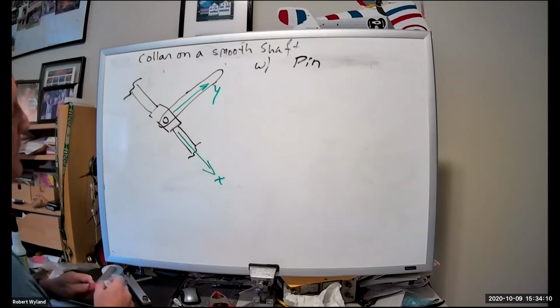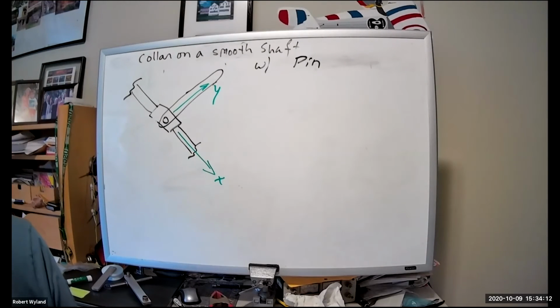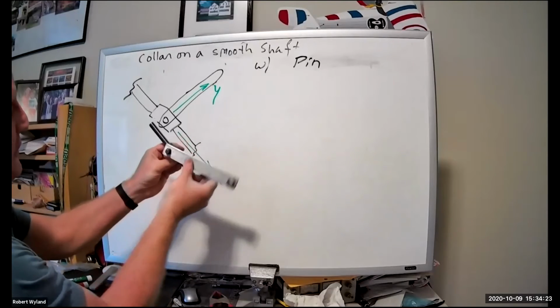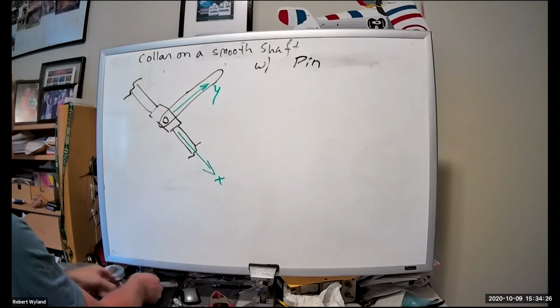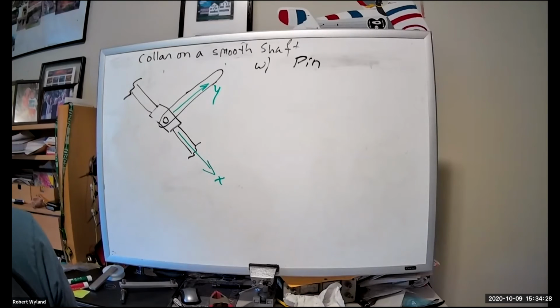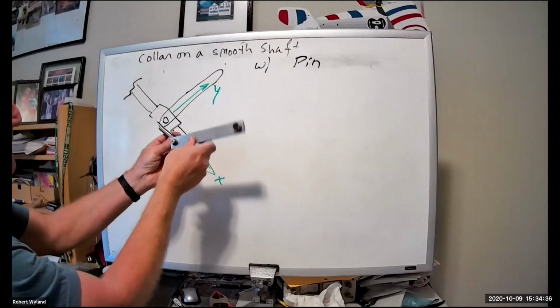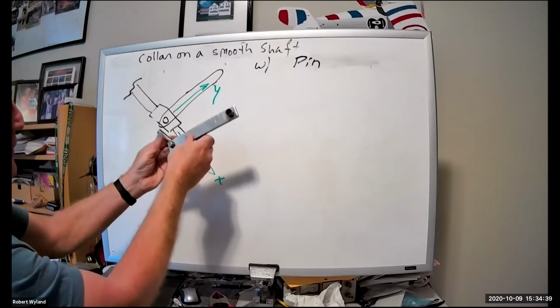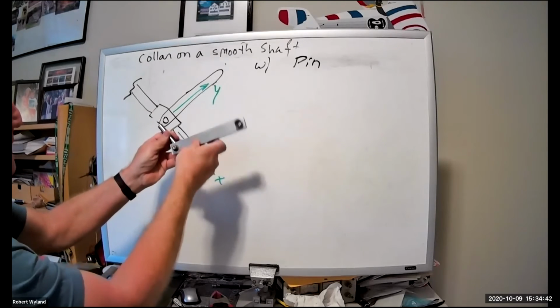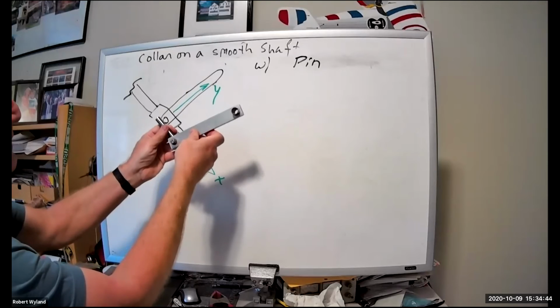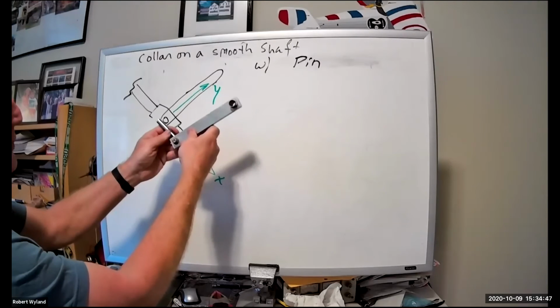So what are our moments? I have a question. Does the pin rotate all the way around, or does it matter if the pin can rotate 360 degrees? So you're asking, does it matter if it rotates 360 degrees? Yes. And the answer is technically no. In most designs, if you were actually designing this, you wouldn't design it so it hits a stop. Then you would start to have other forces on your component. The whole point of putting something like this rotating is usually to eliminate the moment from one part translating to the other.